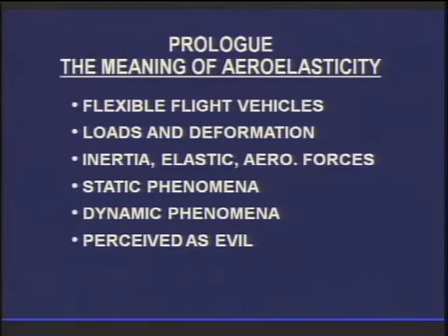Aeroelasticity exists because flight vehicles are flexible. There's a reciprocal relationship between load and deformation. Take an airplane wing: as it flies along, it will deform due to the aerodynamic load. The new shape will change the load, and eventually some type of equilibrium condition will be reached, or an instability will occur.